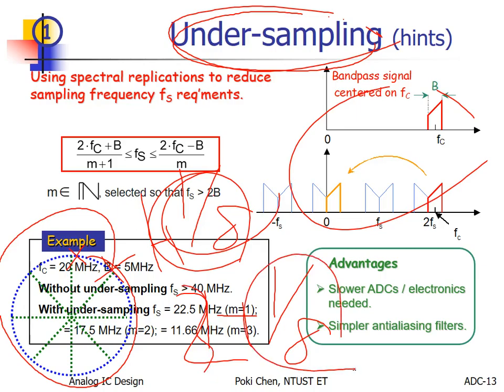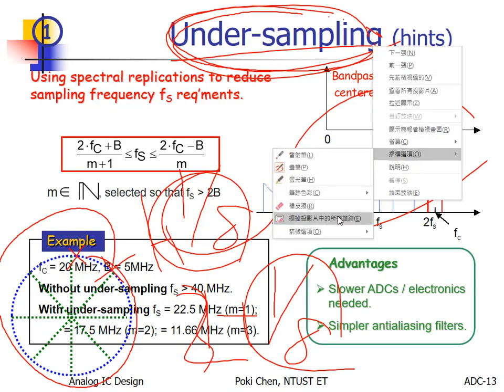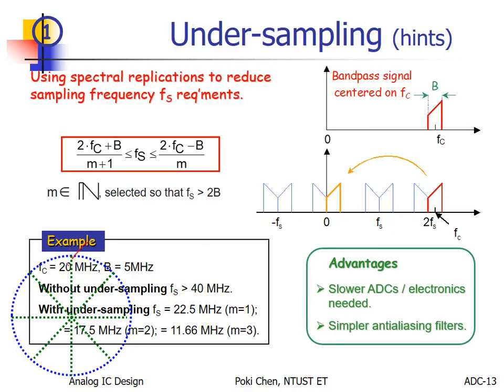Because it is periodic. That is the key word. How to apply undersampling? The signal should be periodic. Otherwise, forget about it. OK? 要使用 undersampling, 你的输入一定要是周期性的。And then you can see, haha, I cannot operate. In theory, you need to say, hey, the first sample here, the second sample there, the third sample.